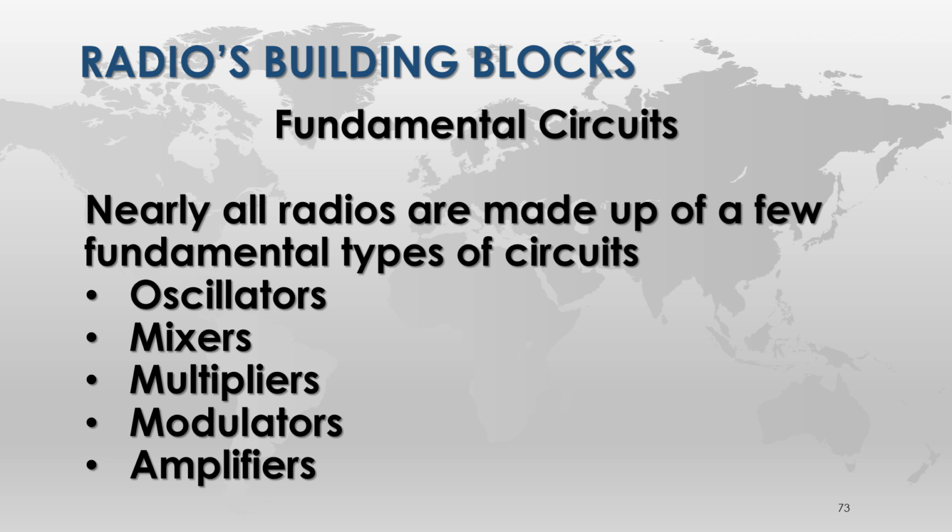What would you need an amplifier for in a receiver? To boost the voice signal. To boost the incoming voice signal that's coming in. The amplifier will take and jack up the voltage because you're bringing in billionths of a volt. And that's not enough to drive anything to process it and spit it out on a speaker. So the amplifier cranks that up. You can also have an amplifier on the outside, on the going out part, because you want to get the power up to whatever you've selected.